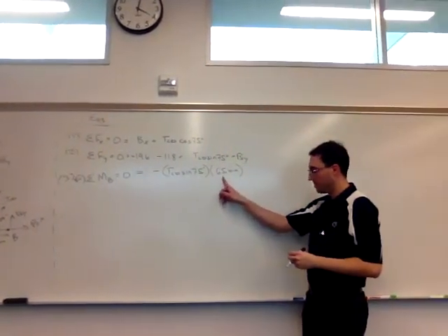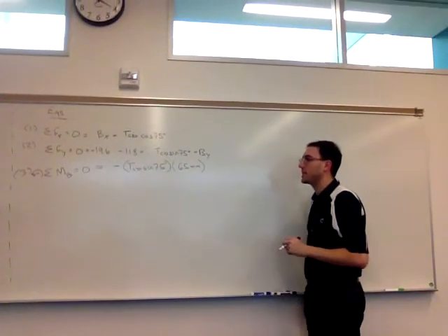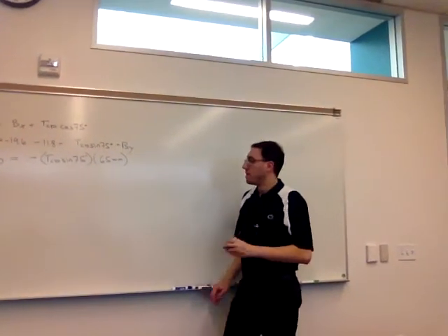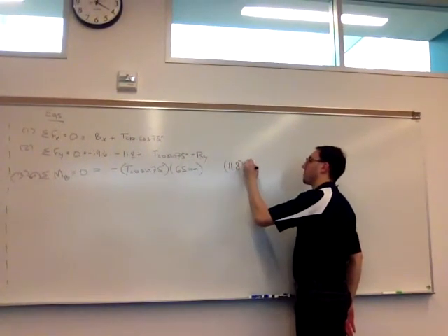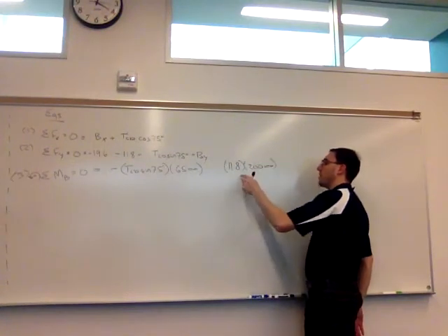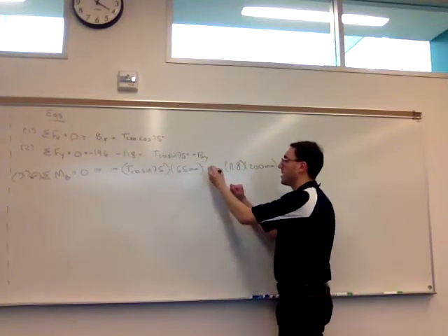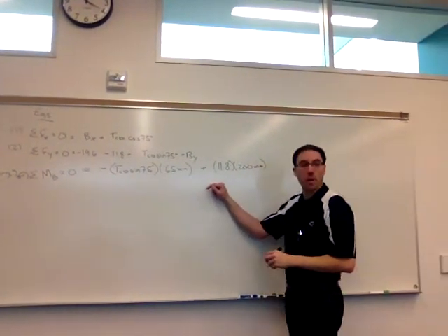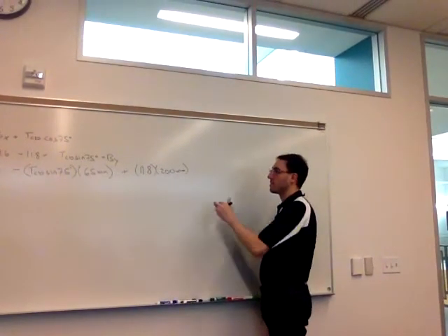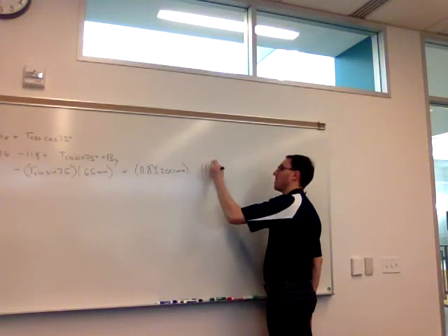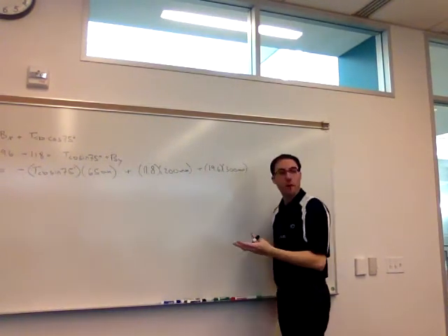All right, so a force, it's times its distance, and it's clockwise. What else is on my right-hand side in this? Plus 11.76. Right, so the force due to the weight of the arm, a distance of 200 from B, and this is positive because it creates a counterclockwise moment around B. And then one more thing on the right-hand side. Right, so again, the weight of the beverage.